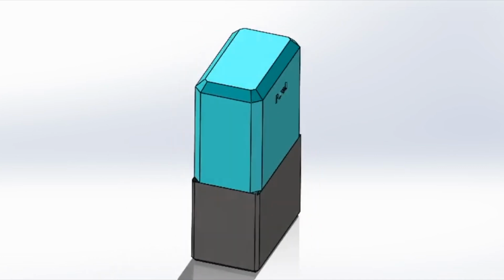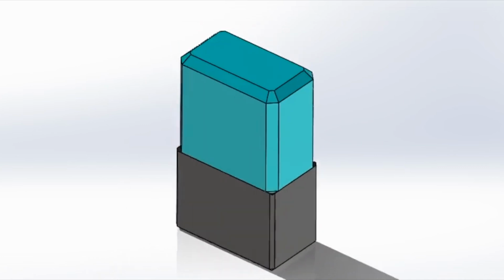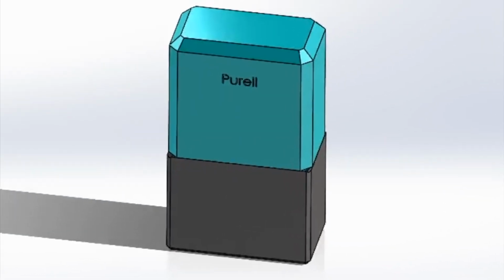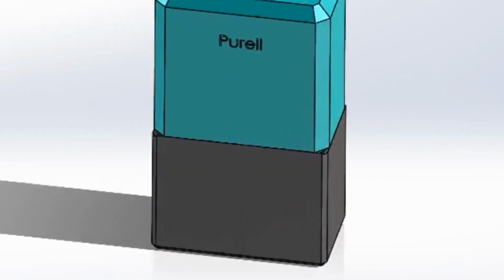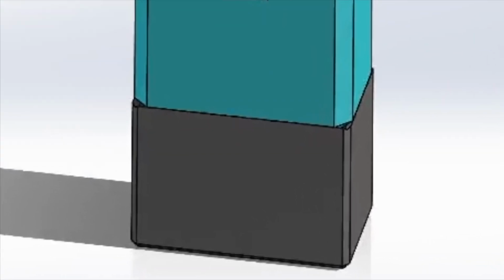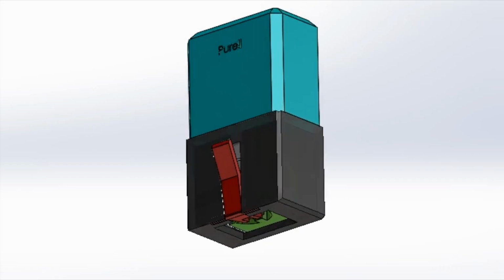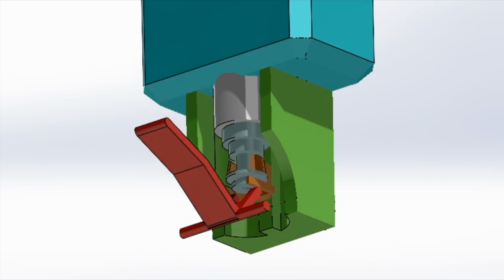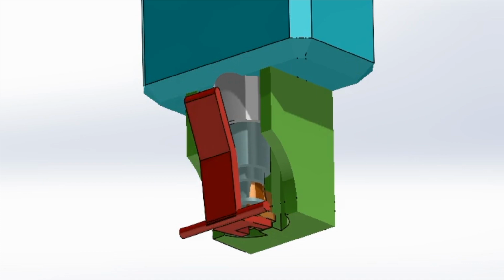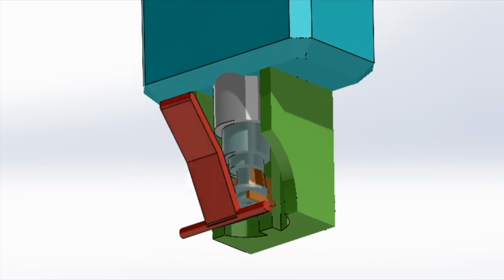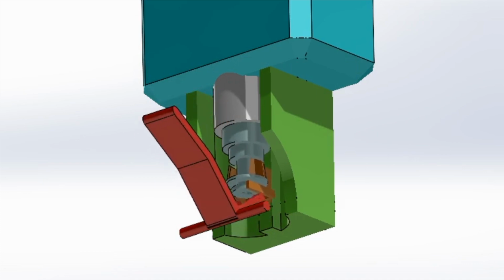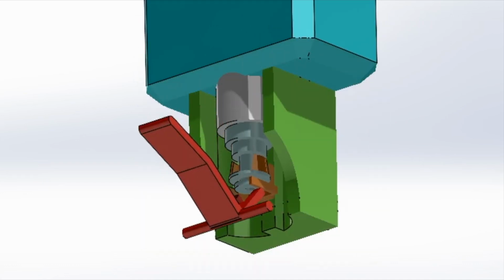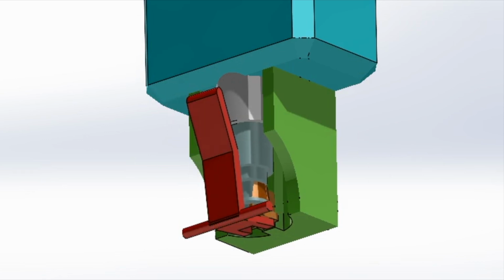The endless complications that are present can be swept away with a very simple adjustment: creating a manual failsafe that coincides with the automated function. Introducing a mechanism that allows the consumer to manually control the dispenser will resolve any potential problems. Here is a design of the manual failsafe. It is a lever that, when pulled, applies force on the nozzle and releases a pre-measured amount of soap.